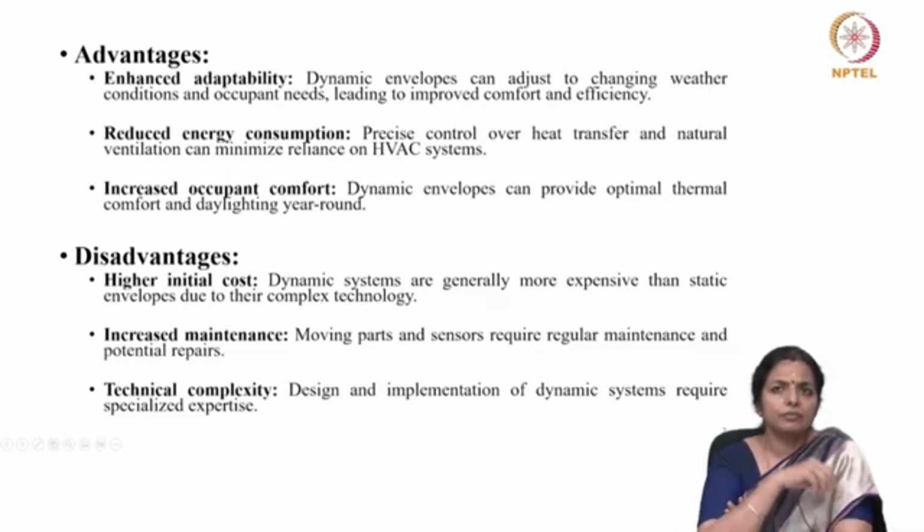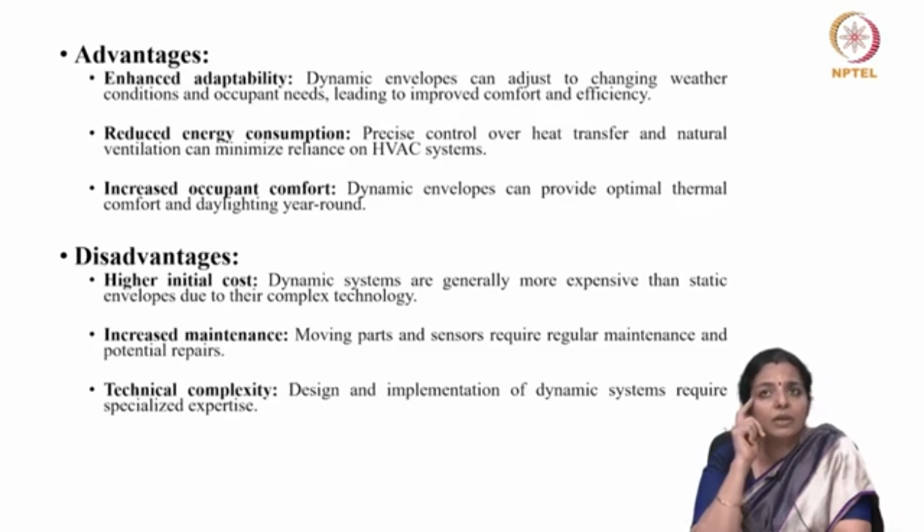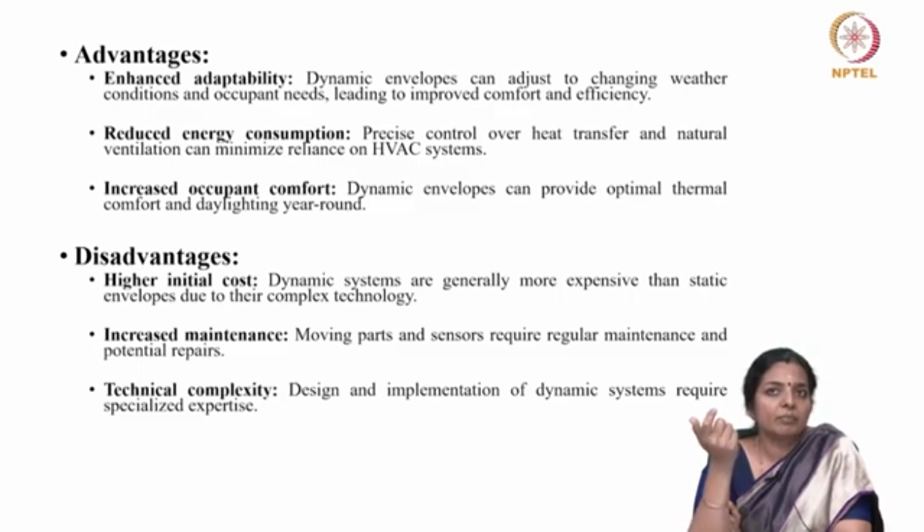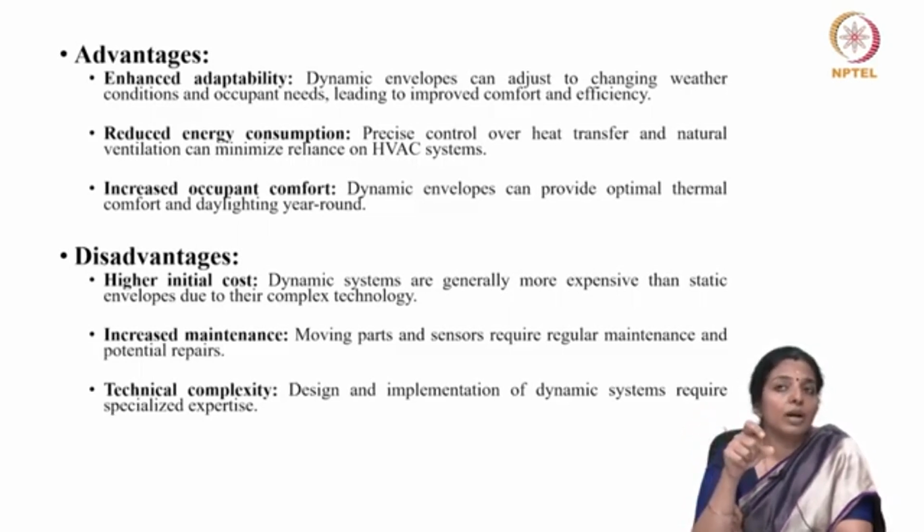So, a building envelope is critical in determining energy efficiency in buildings. Because it is the shell of the building that acts as a barrier between the conditioned indoor and the outdoor environment, nearly 50 to 60% of heat transfer and heat exchange happens through this building envelope and can result in 26% of the total building energy load due to the heat gain.